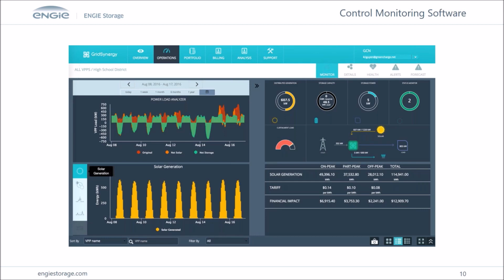I think one of the unique things we've learned over time is that the variability of solar can dramatically change the savings from an energy storage project. By taking that solar production data and creating a local expectation of what's being produced from the solar system, you can create significant increases in savings with the storage unit. So really integrating the two systems is key. We're also starting to see more DC coupled systems where the solar system and the energy storage system are combined on the same inverter.